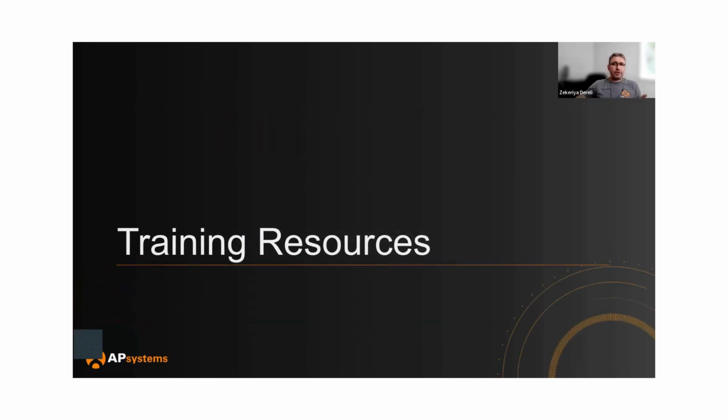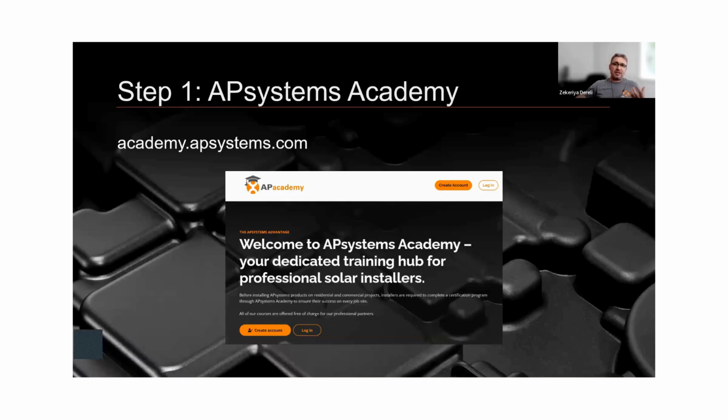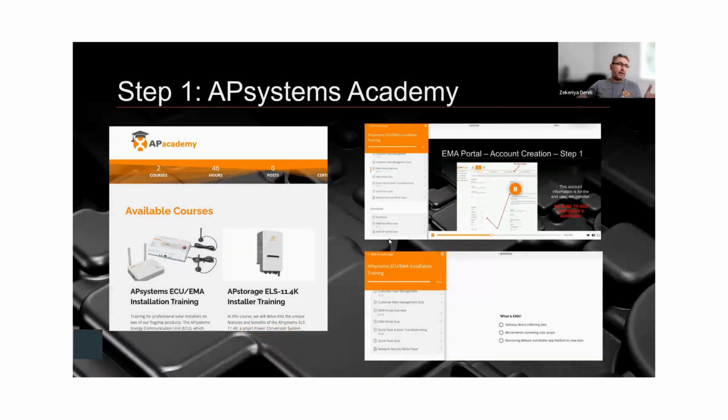So for the training resources, we have AP Systems Academy, and we strongly recommend our installers to go through the ECU training at the bare minimum, because whether you're dealing with the storage or not, you're always dealing with the ECU. That's the equipment that you have to work with to commission the site, to access all the inverters, and do all kinds of settings, the mapping, etc. So you really need to understand how the ECU and the EMA works.